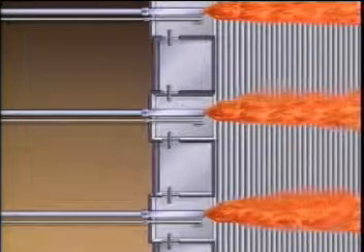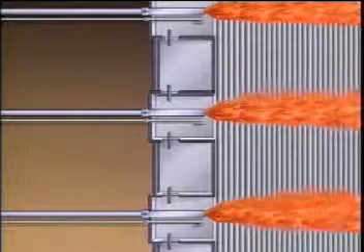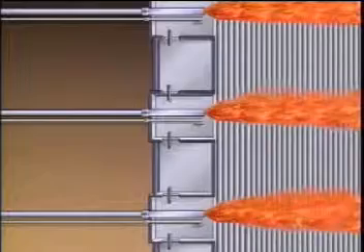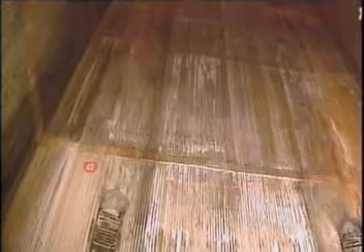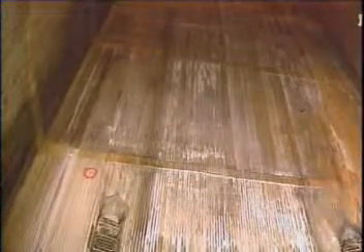Once air, fuel, heat, and turbulence have been provided in a controlled manner, the chemical reaction of combustion can take place in an efficient manner. The time element of combustion is satisfied by the design of the furnace as a large open space in which fuel and oxygen have time to mix thoroughly and react completely.